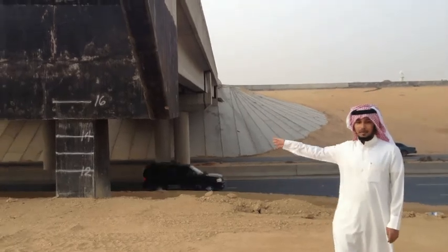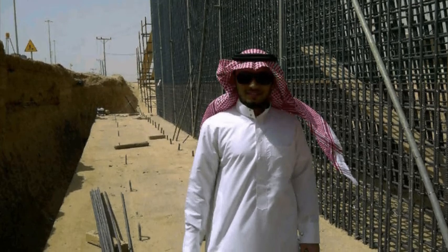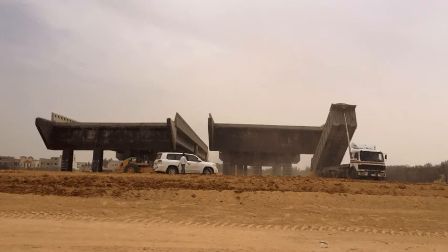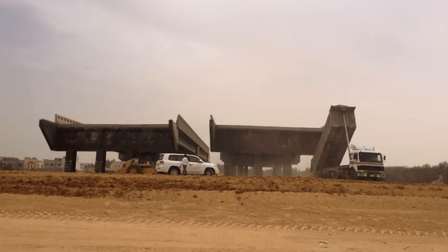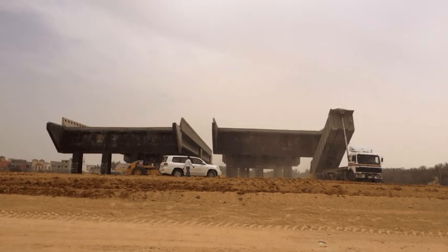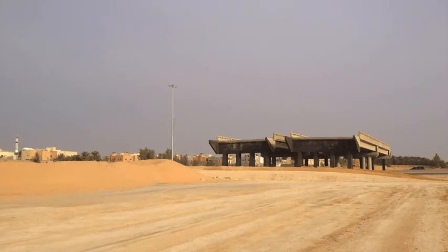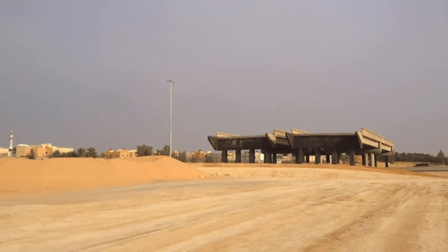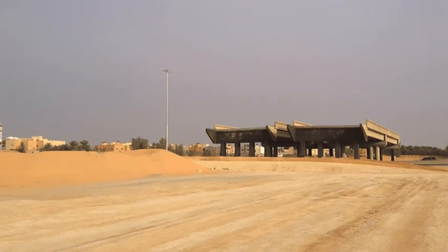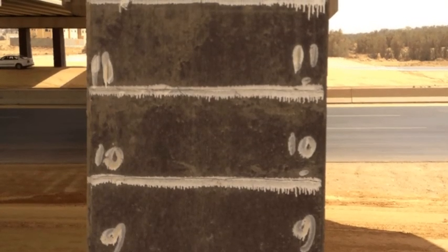The general elements of the bridge are the superstructure and the substructure. Foundation is the first step toward building a bridge. This process involves a detailed geotechnical study of the bridge site. The type of bridge foundation has to be selected, such as a well foundation, pile foundation, or open foundation. Each foundation is suitable for a specific soil and desirable bridge characteristics. The soil characteristics will determine the load capacity and other important parameters.